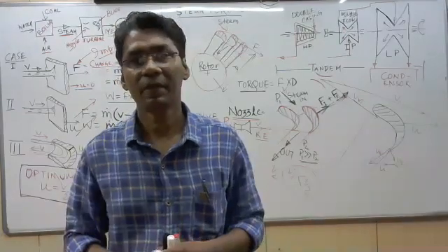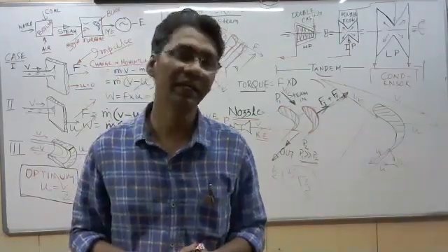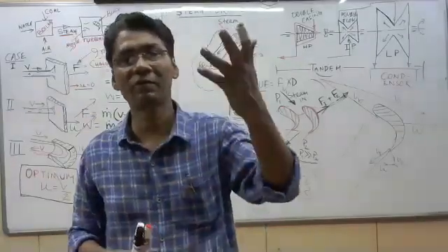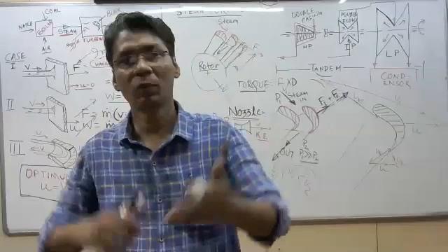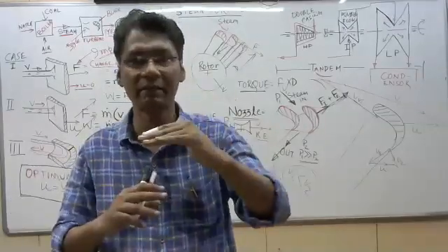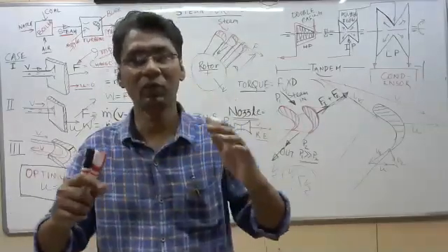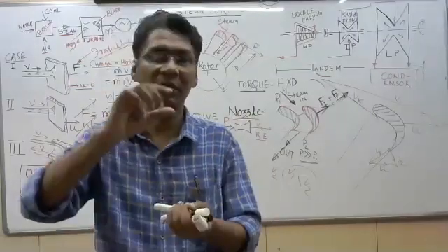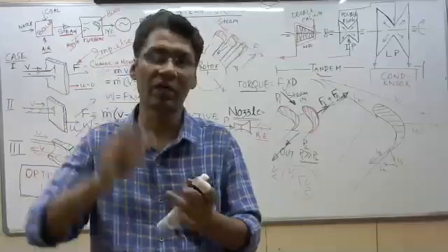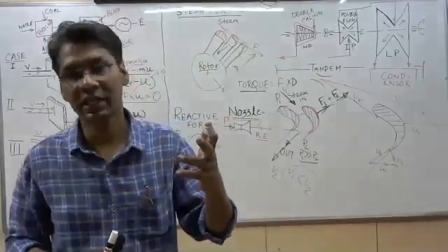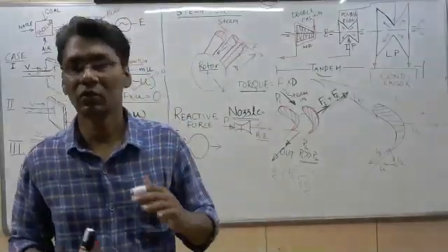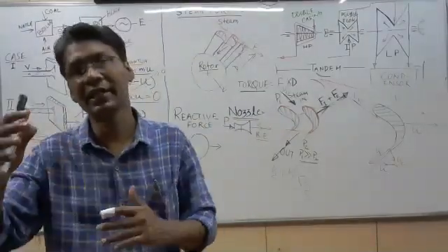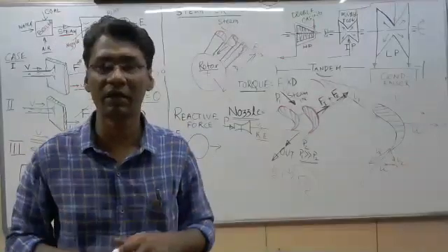A double casing turbine is designed. If the casing thickness is higher, it will take a lot of time for heating or starting. To minimize the turbine starting time and heating time, we design the high pressure turbine as double casing type. With double casing, the casing thickness becomes lower. The detailed discussion cannot be done within 1 hour. So to avoid expansion issues and to reduce the heating time of the turbine, we design the double casing type.